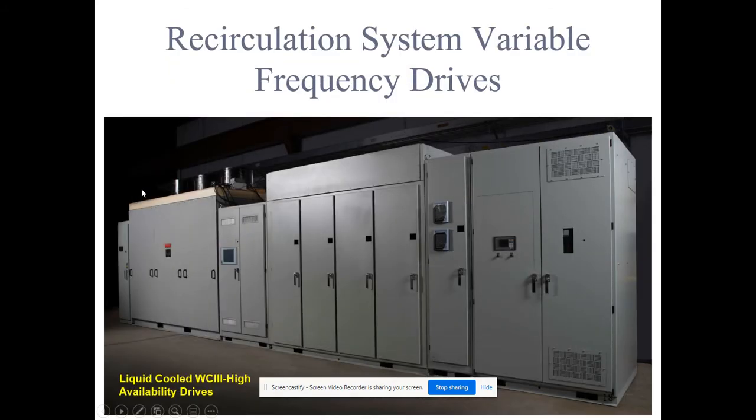So how are we going to control flow? This is not something you need to know too in depth and in detail, but it's a variable frequency drive. So it's relatively hard to change a pump in such a way as to change flow. That is not an easy thing to do. These big things, these are like the size of a school bus, are basically designed to give you a variable frequency and a variable current so that you can change the speed of those recirc pumps.